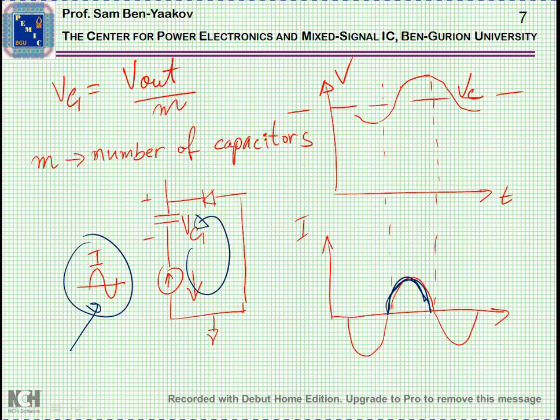As soon as the current starts to flow, the capacitor will charge up to the point that the current stops, and then of course, because of the diode, there's no negative current, and in the next half cycle, the capacitor will discharge because it will be delivering the charge to the corresponding capacitor. So a current source is really a neater way, except that it usually requires extra electronics circuitry, because we don't have natural current sources.